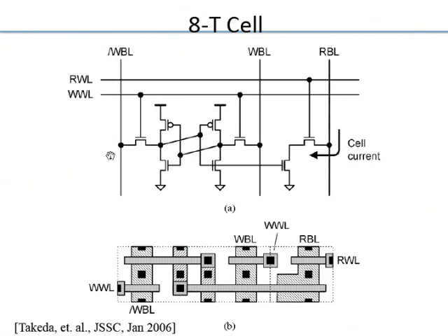And then because the 0 can be here or here, you have to have the ability to push a 0 from both sides depending on the data you write. So you need to have both the bit lines. If you remove this, then you have to be able to push a 1 or a 0 from both sides, which means you need to have a transmission gate. So that is possible.